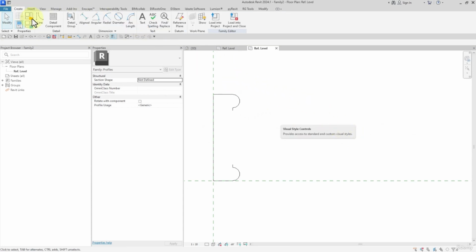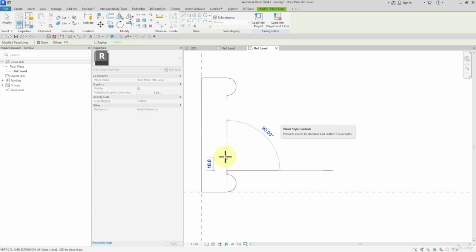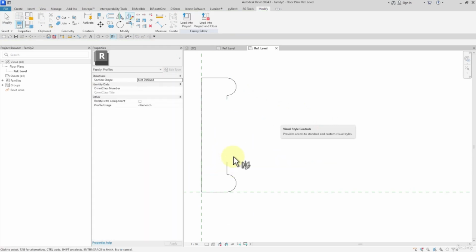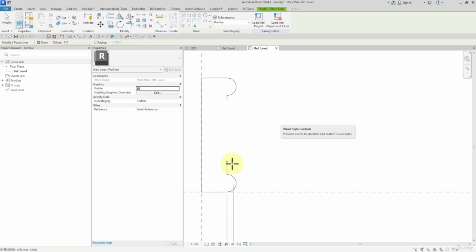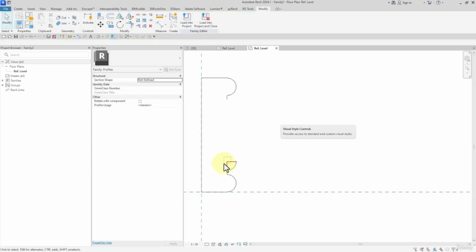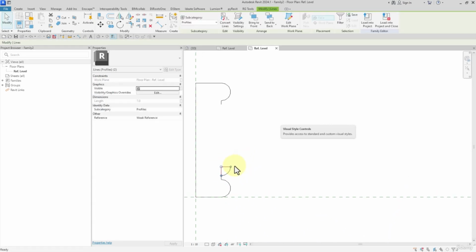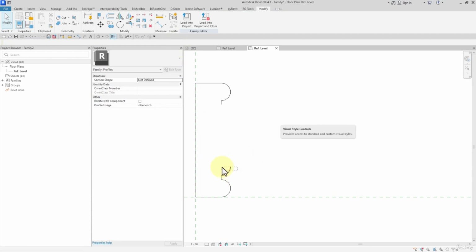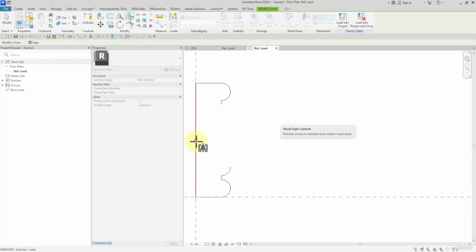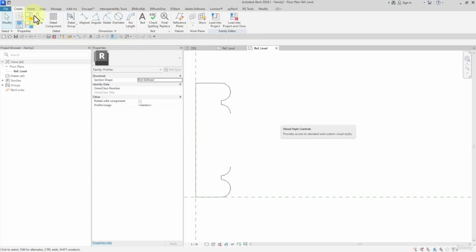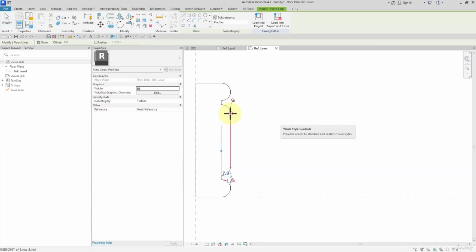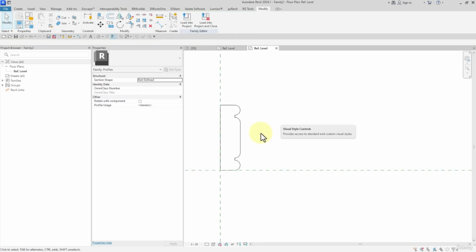After that, I want to draw a line 7, again line and 7, then center. Watch this. We draw the arc and we delete the redundant parts. Then I select the arc and I mirror it at the other part. Then picking the line and connecting them to each other, like this way.